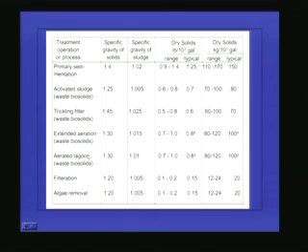In an aerated lagoon, the specific gravity of the solids is 1.3 and the specific gravity of the sludge is 1.01. For filtration, it is 1.2 and 1.005. And if you want to remove the algae from the oxidation pond, the specific gravity of the solids is 1.2 and the specific gravity of the sludge is 1.005. These values are very important because they decide the volume of sludge we have to handle, and the volume is very important when we design the treatment systems.